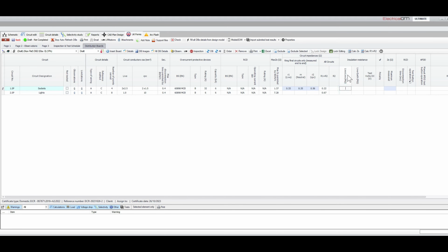Now the insulation resistance values, the live to live, so that's between your line and neutrals. Obviously we had a 0 value on those, but it is to do with the equipment that's connected into the circuit. We had issues with the USB socket and also with the lights that are still in there and the circuit boards and so forth. So it's really difficult on an existing installation with lots of equipment connected to disconnect all of that and take a measurement. So you can either make a limitation of it and you can record the value of 0 if you want, because that is effectively what we did record, but we know that there's an acceptable reason for that to be the case. I'll just pop 0 in here for the minute because why not, and we'll note it.